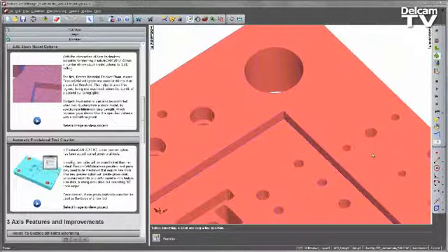With the introduction of new technology toolpaths for finishing, FeatureCAM 2013 R3 has a number of new stock model options for 2.5D milling. The first, detect material thicker than, means FeatureCAM will ignore rest material thinner than a specified threshold. This helps to avoid thin regions being rest machined where the benefit of a second cut is negligible.